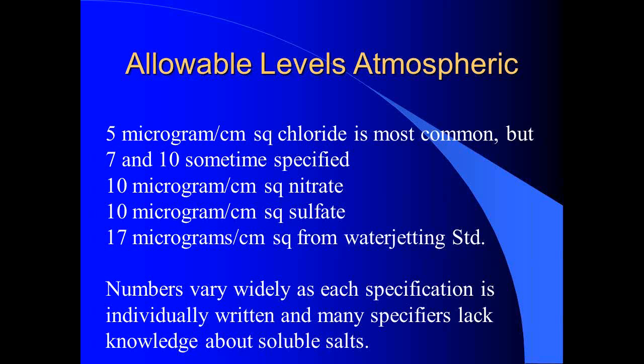I asked Lydia Frenzel one day, the chair that chaired that document when it was written, how did you ever come up with a number like 7? She said, well, we had a lot of bridge people in the room, and everybody pretty well agreed that at 10 micrograms, they were still having excessively high failure rates, but at 5 micrograms, they were having what they considered adequate performance.